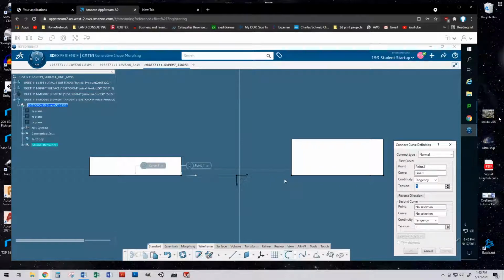Watch the pop-up window, guys. Can you highlight the pop-up window where we're at and what's the next one? Sure. So I need to pick my line here, and then I chose curve, so it's going to automatically fill that gap in. It's just, we're going right down the list. You don't have to remember the order, just follow the pop-up window. And then the flow lines are in the right direction.